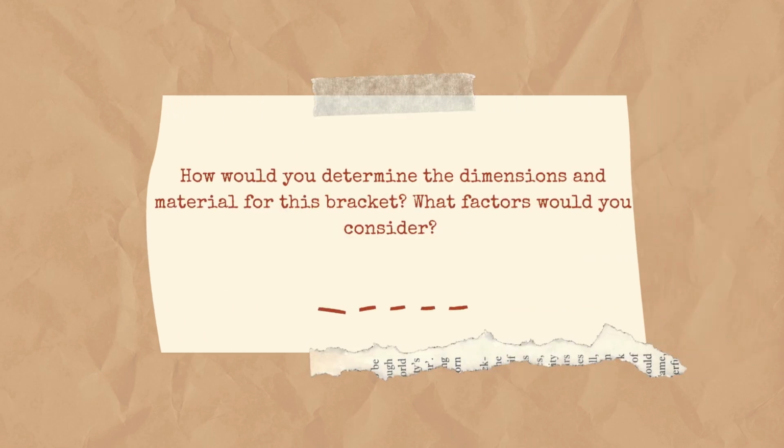Imagine you are designing a spreader beam for lifting and handling that must support a load of 100 T. How would you determine the dimensions and material for this bracket? If I'm going to design a spreader beam for lifting and handling a 100 ton load, I will select the suitable beam and sling. First, I will draw a free body diagram to do the force analysis and determine the strength of the beam and the sling that can withstand the 100 ton load without failure.